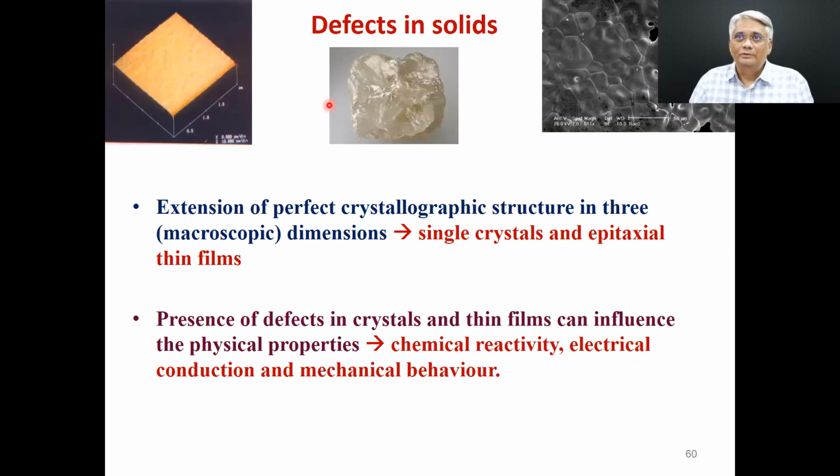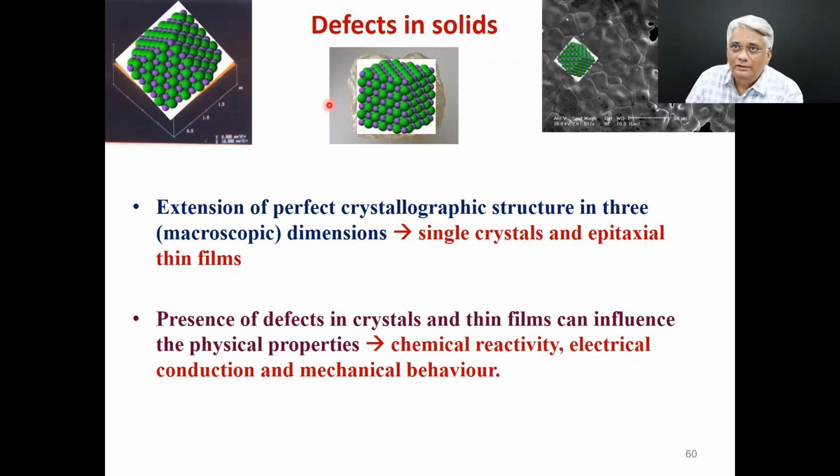But when you come to the bulk counterpart, the polycrystalline material, if you take that grain, a single grain is single crystalline, a neighboring grain is also single crystalline, but you have a grain boundary that separates them. And between grains, the orientations of the ensemble of these unit cells can be different, right? So you may have different orientations. All these small crystalline regions are separated by grain boundaries, which are unwanted, which are detrimental to physical properties.